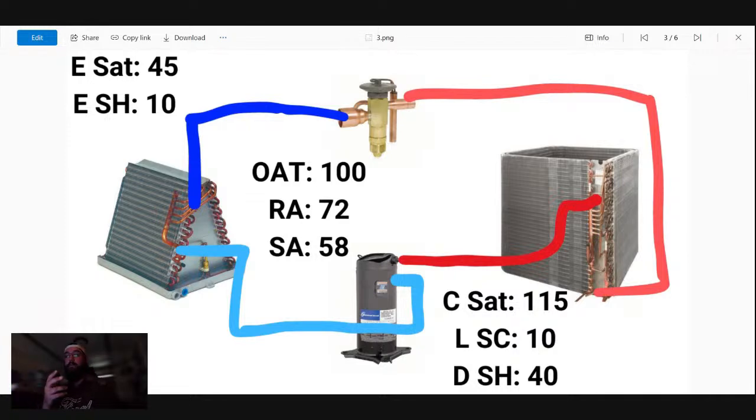That's been mentioned a couple of times here. We're going to lower the fan speed. I would recommend, typically I start at medium, see how we do. And if I still see that we're running higher saturation, so 45, if it's a house that's going to deal with humidity issues, and if they do have infiltration problems, then we're going to have more humidity than we normally would to deal with. So I wouldn't want a 45-degree coil in a space like that. I'd much rather see that much lower down.